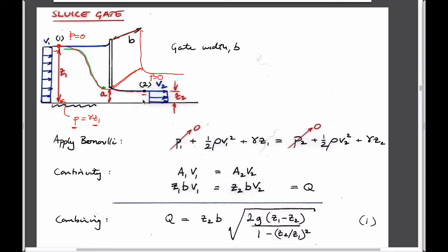So the elevations we know because you can measure that relative, so we can get rid of this term and this term. So I guess it's the opposite of the other case. Before, the elevations were constant along this center line of the Venturi flume, and the pressures were non-zero. And here we have the pressure 0 and the elevations are non-zero. So this is just Bernoulli's multiplied through by the unit weight of water on all sides, right? All terms.